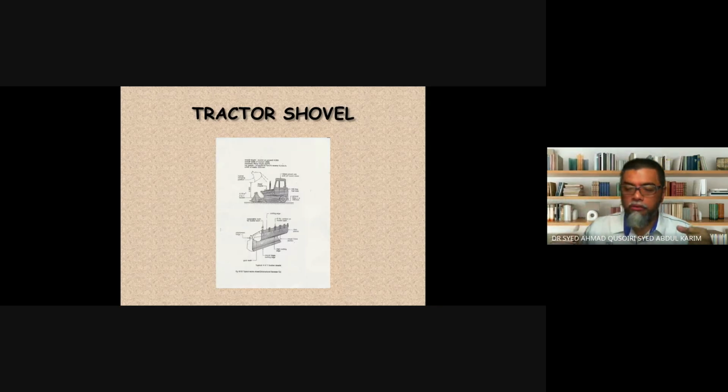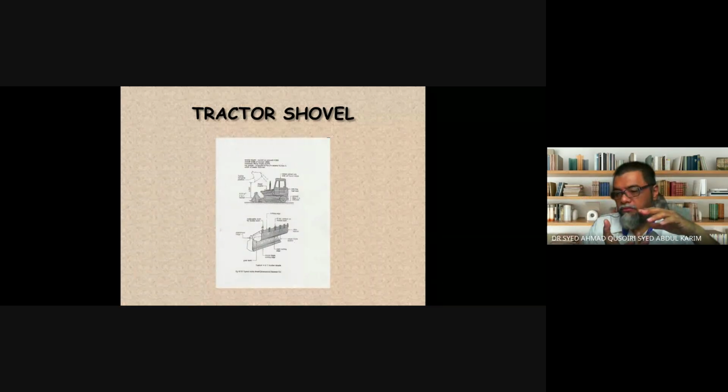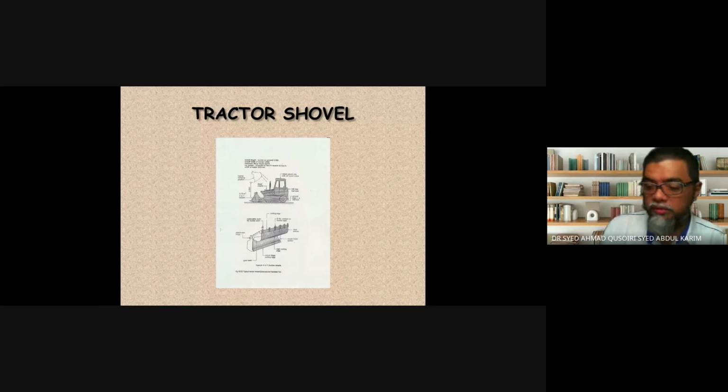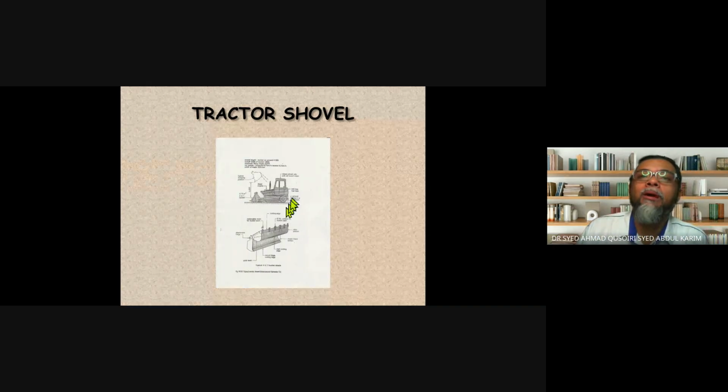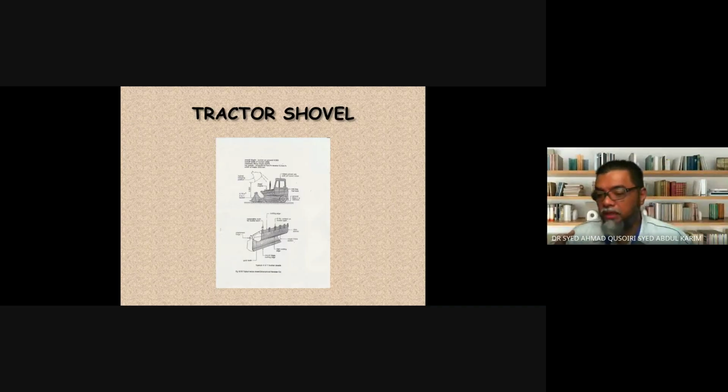So you need to use the momentum or the mass of the loader, really drive it into the spoil heap so that you can fill the bucket as much as possible. But if you use the chain type, you can't really go as fast. You would rely on a very powerful engine to fill up the bucket at the front, because it can't move fast, right?